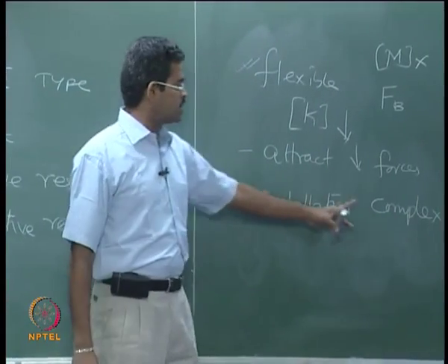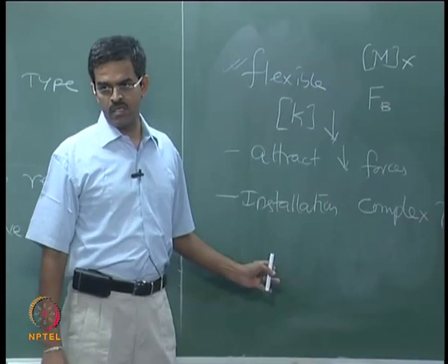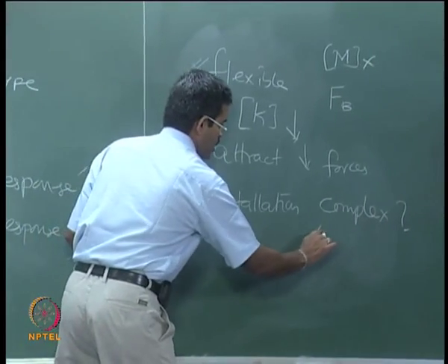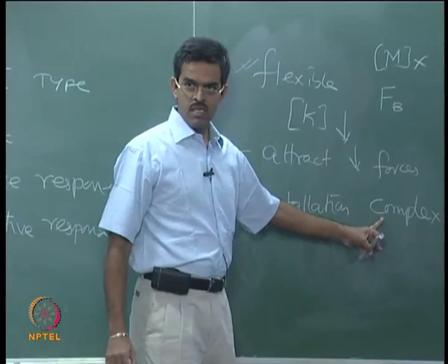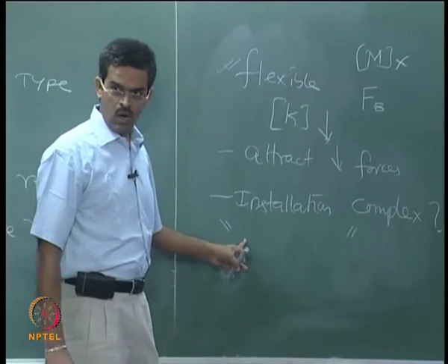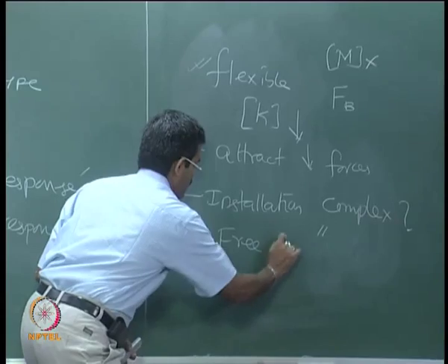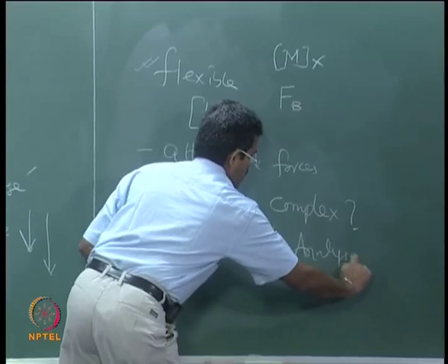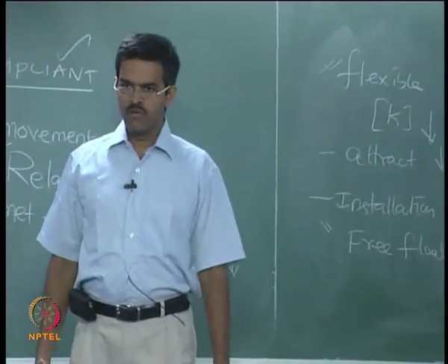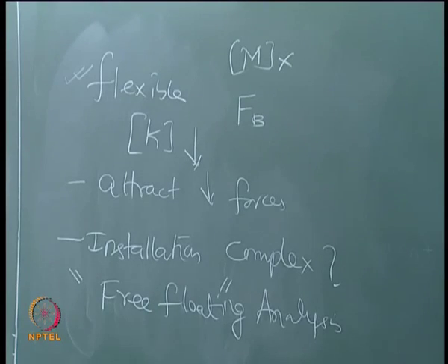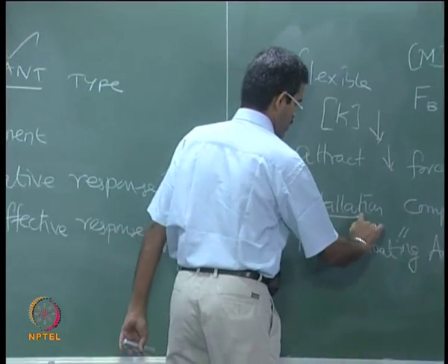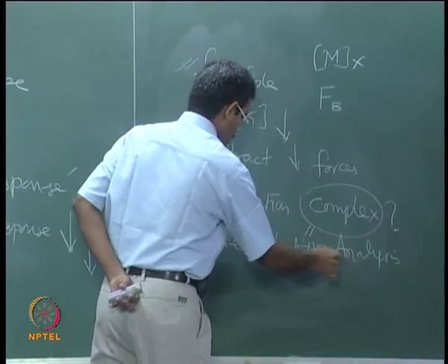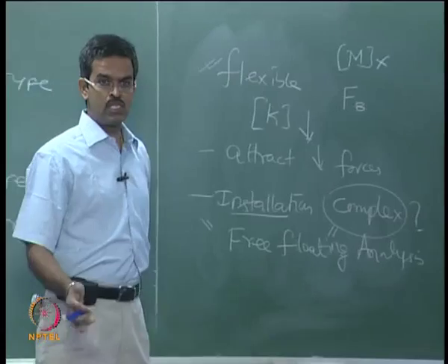So, how will this complexity govern the dynamic analysis of such structures? To a very simple question, the answer is that the governance of this complexity in dynamic analysis will focus on free floating analysis, because while installing, due to the complexities introduced by the form, the structure may become dangerous in the free floating state.